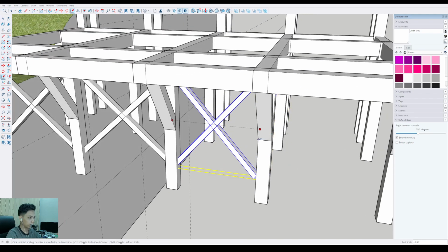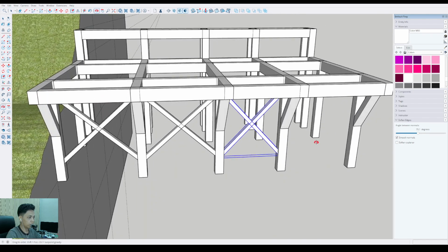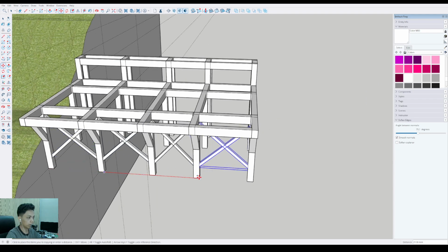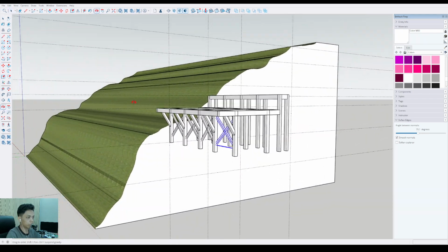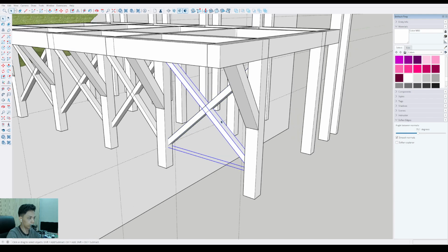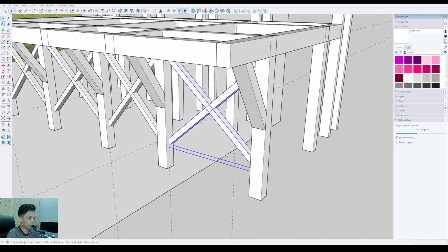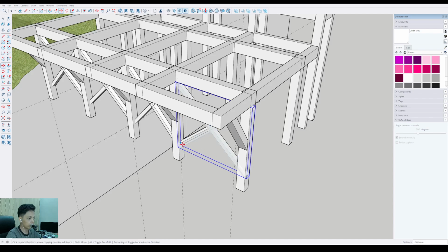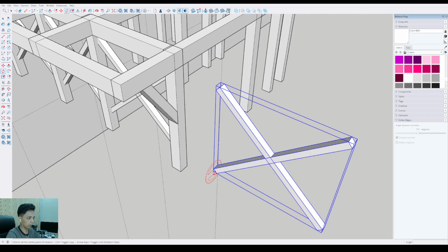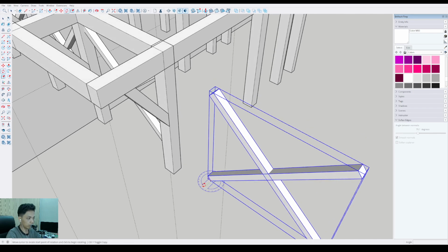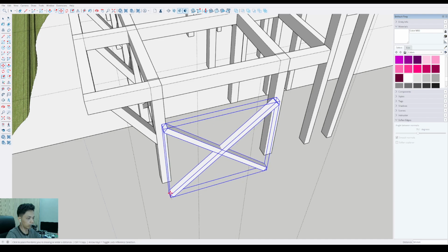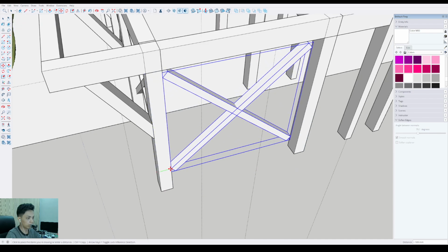It's just for example, but I suppose to show you how to make the bracing system in this SketchUp. Okay, so you can click this bracing only, and then you can right click and make group, and then you can select move and press Control until this position, and then you can rotate it. You can rotate it. Okay, and then type 90 degree. Then you can select move and place to the another position.